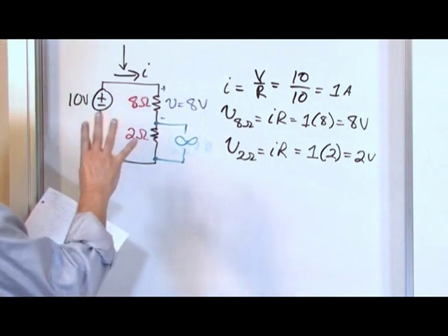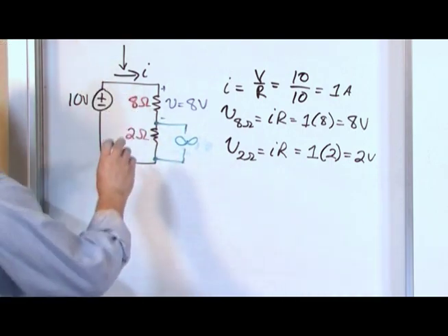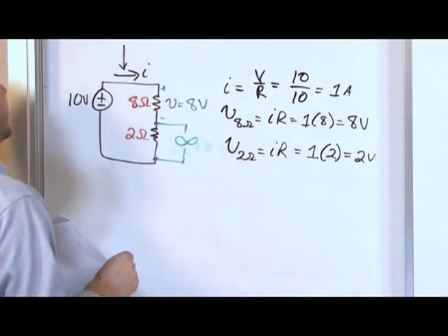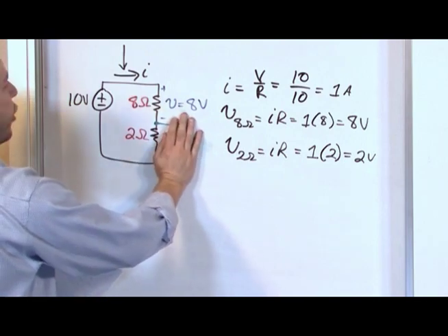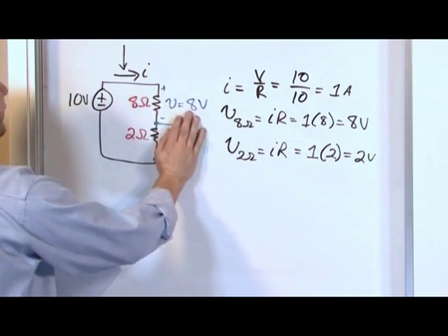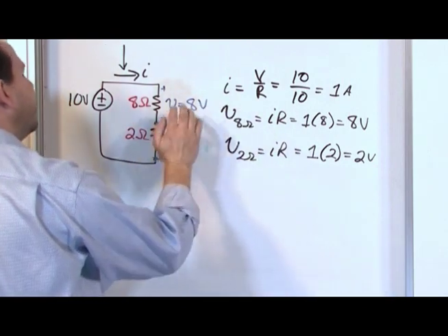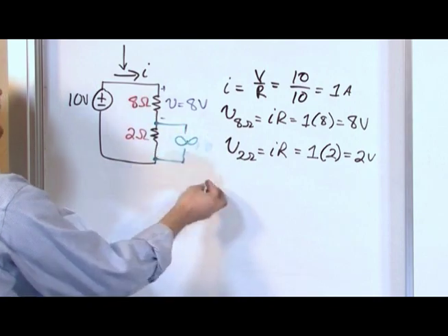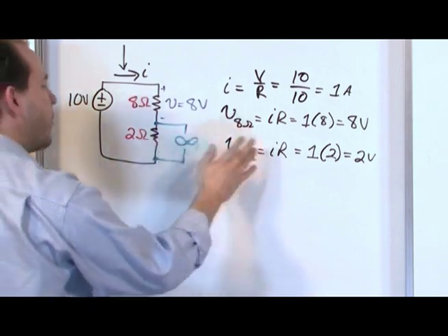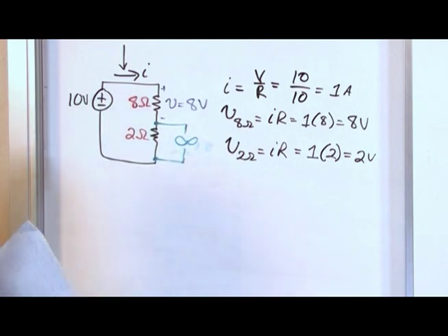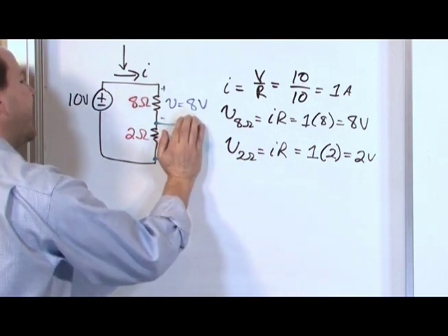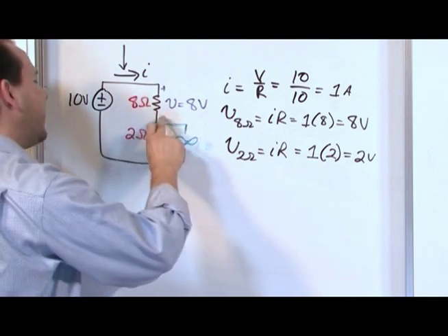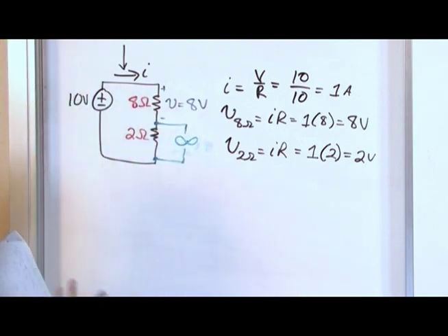All right, so to recap before we do a problem, here's a voltage divider. I'm going to show you how to calculate easily how the voltages are divided in a second here. If you don't have any load connected at all, it's called the no load voltage on my output terminals. Once I connect something to it, it's called the loaded down voltage. And depending on the resistance of whatever I hook up, I may change things a little bit and maybe I won't get exactly 2 volts out. The higher the resistor value of whatever I connect here, the more pure my original voltage divider is, and the exact amount of voltage drop that I calculate is what I'm going to actually get.